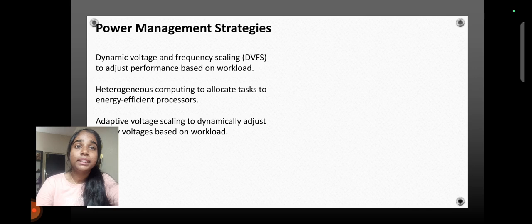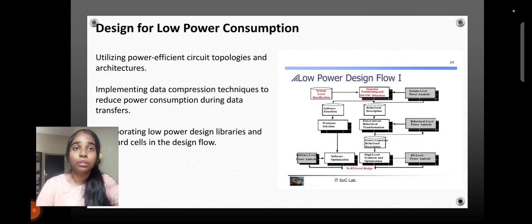Power management strategies are dynamic voltage and frequency scaling, that is DVFS, to adjust performance based on workload. Heterogeneous computing to allocate tasks to energy efficient processors. Adaptive voltage scaling to dynamically adjust voltage based on workload.